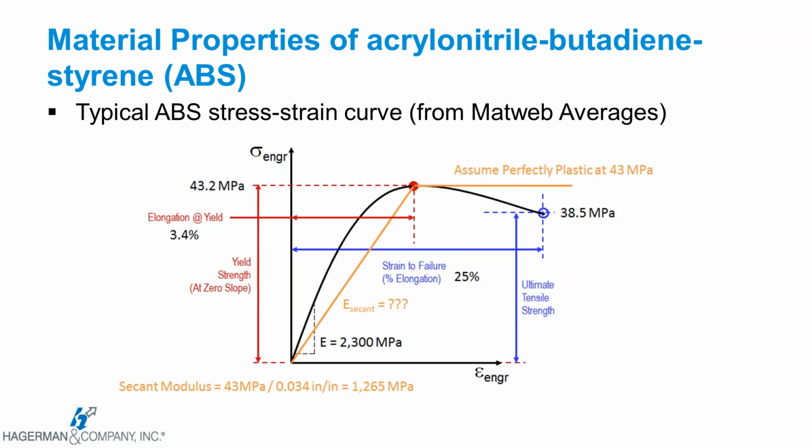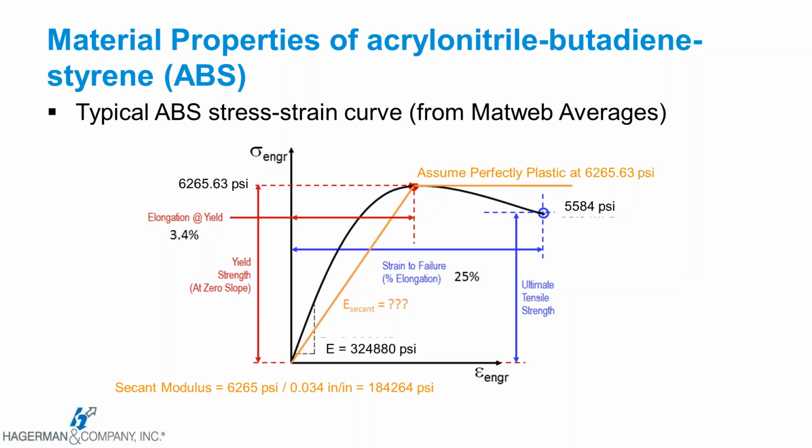And so I went through and tried to adjust these values to continue using our English units as we had been using. The system is intelligent enough to know the difference. So if I were to go in and start specifying, say, 43 megapascals versus a PSI value, it would just make the translation. That was a new feature in 2017. It knows the conversion on its own. But in my case, I've already done all of that work ahead of time.